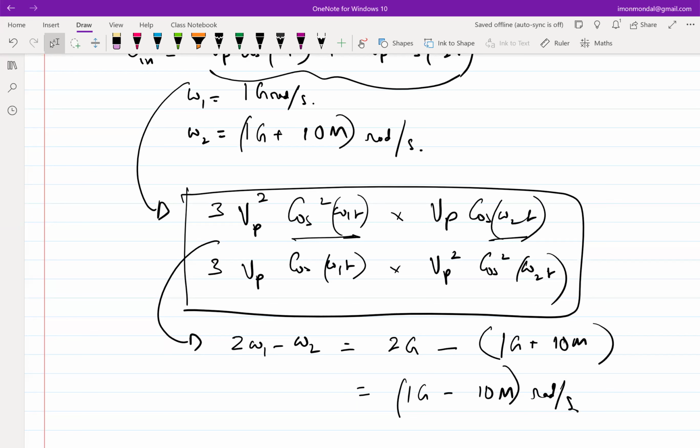In fact, that's why there are certain specs. It's called adjacent channel leakage ratio, ACLR, which essentially means that you stay in your lane. Basically, I don't care how nonlinear your device is. Even if, let's say, I'm designing a power amplifier, and I know that the maximum power that I can transfer is 0 dBm, you have to ensure that anything out of that band, including your distortion components, has to be lower than, let's say, minus 50 dBm or minus 60 dBm.